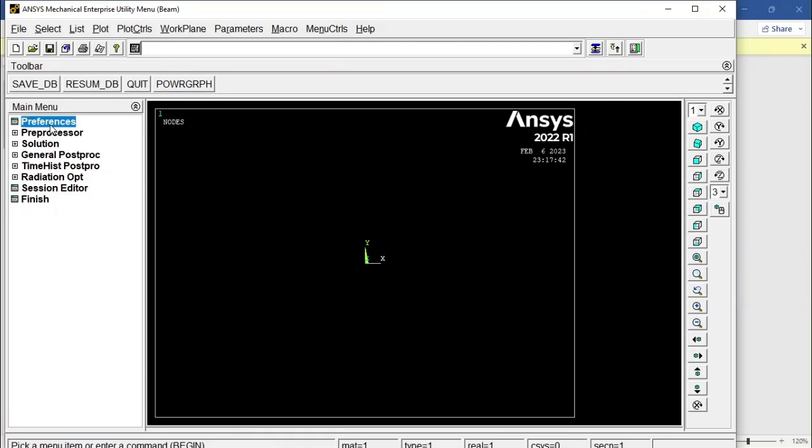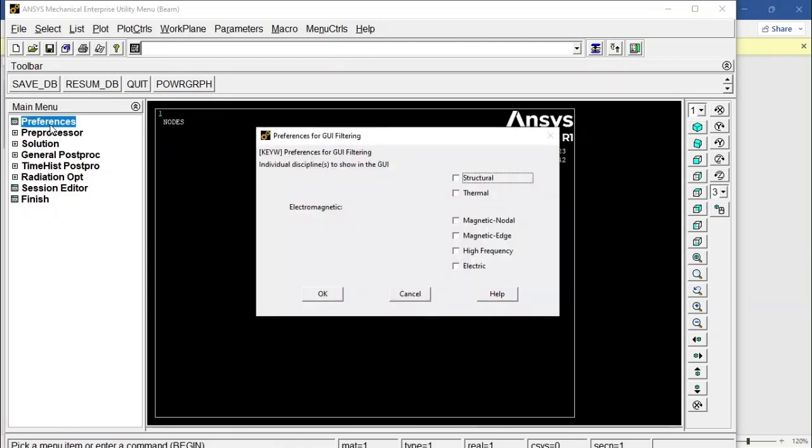Before going there, I would like to tell you about the unit system in APDL. Unless we are choosing anything from the material database, the system is not following any particular unit system. So whatever units we define or numbers we take, the system will give us the result based on that. Either you can go for all the data in SI units, or you can select the unit of length as mm. Then accordingly you have to select Young's modulus and other strength parameters in megapascal.